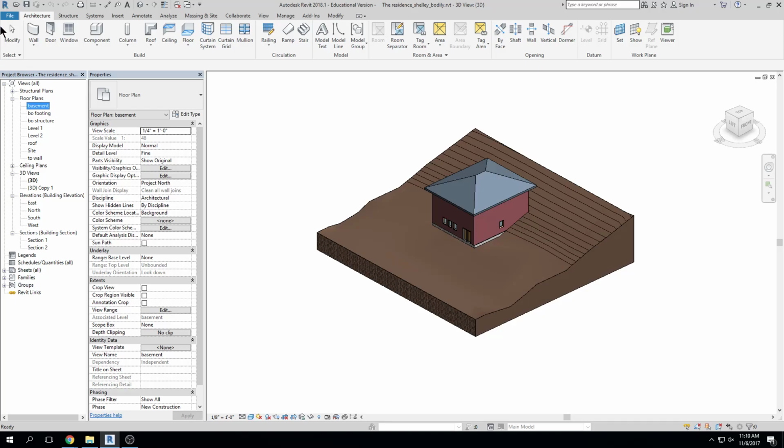several very well-defined phases of architectural drawings, right? We have programming, where you sit down with the owner and you determine requirements for their project. You have schematic design, where you work through all of those requirements and come up with a basic design. You have design development, where you refine that design into actual architecture for the client. And then you have construction documentation, where you have the design of their project pretty well finalized.